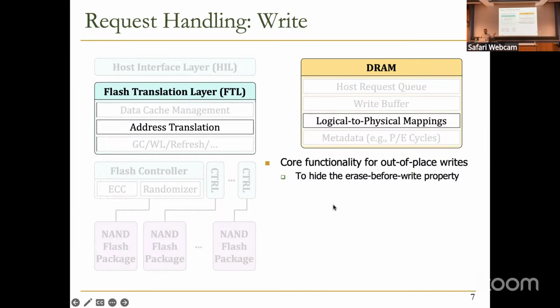So one thing which we're going to see also later, in flash chips, in flash cells, you cannot update. So when you write, and when you want to write something else, you first need to erase it and then write it. So there's a property which will be clear when we start about that. That's an erase-before-write property which we have for flash chips.